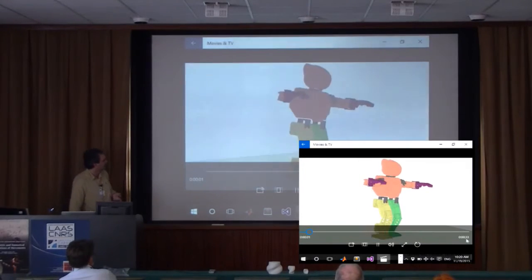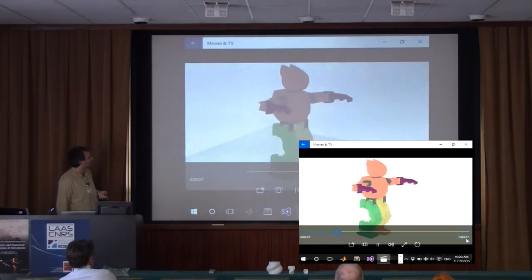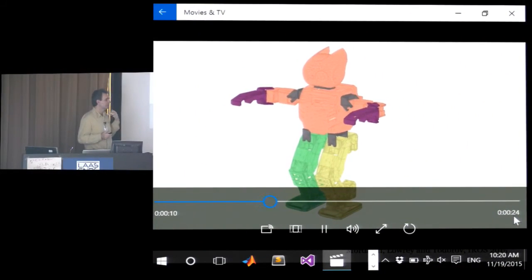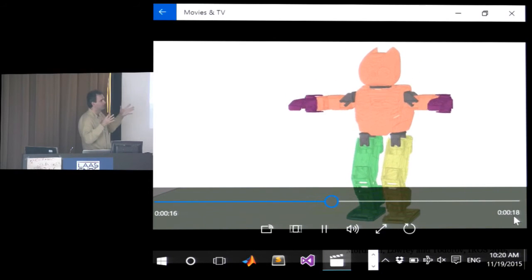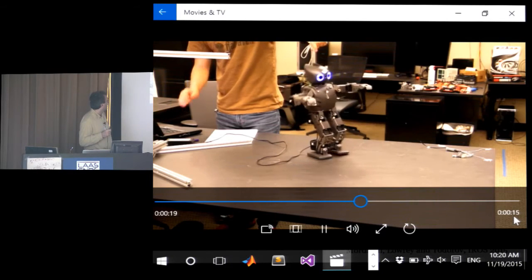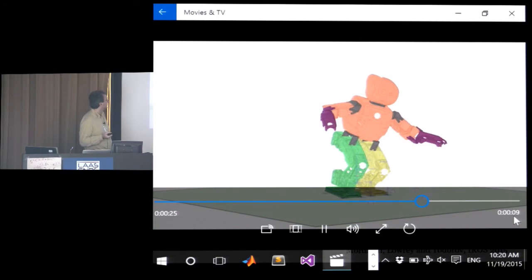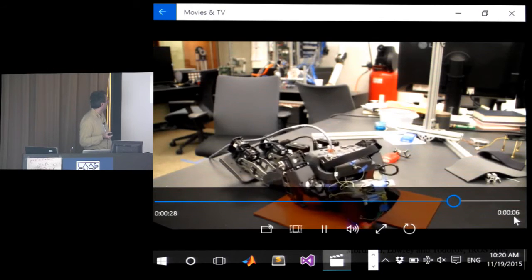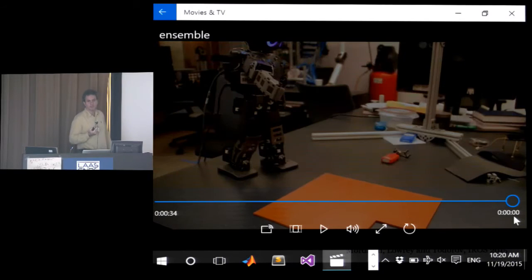Okay, so here are a few illustrations. Here's an optimization of stepping. And here's the thing running on the little robot. The motion looks quite different because we're not sensing where the root is. We're just sensing the joint angles. So the root can actually fluctuate while the joint angles are very accurate. And it kind of does, so the trajectory is actually quite different from what we planned, but because of this robustification step, the thing actually works. Here's a complicated multi-contact getting up from the table. And so these things work about 85% of the time. The other 15% they fall or they get stuck. So it's not perfect yet. I think if we add sensing of the torso, it's going to become a lot more perfect, actually.